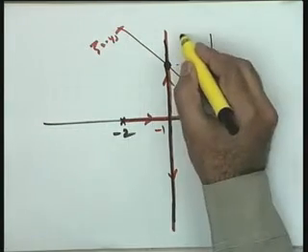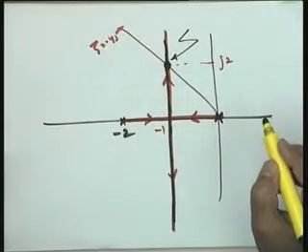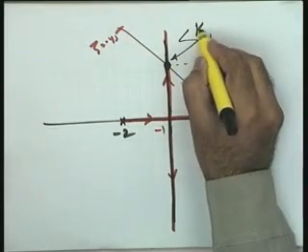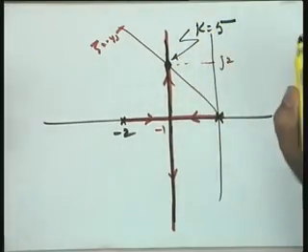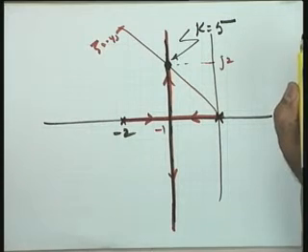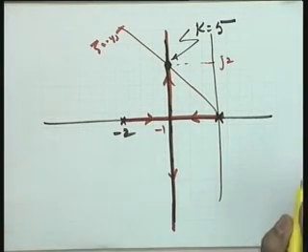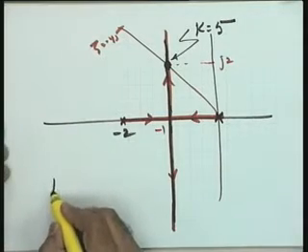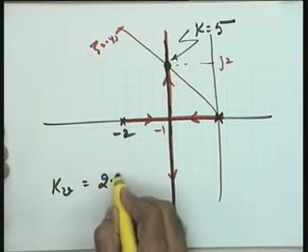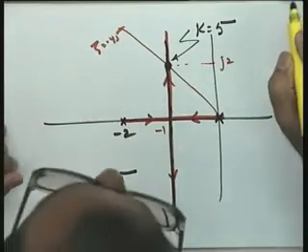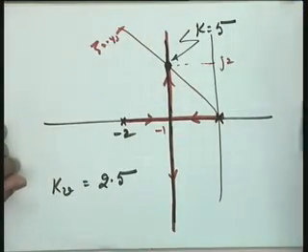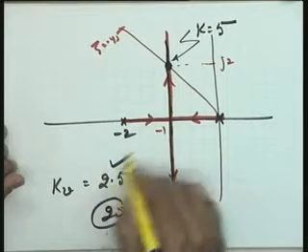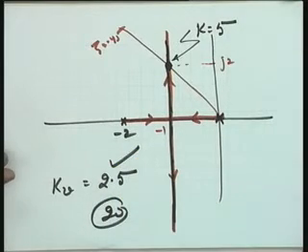Please see. Let me first of all get the value of gain K for this particular case. The gain K comes out to be 5. So it means K equal to 5 satisfies the transient performance requirement. Let me simply check the steady state accuracy. Kv in this case will turn out to be 2.5, because K by 2 is your Kv, which falls short of 20 by a large factor. So the uncompensated system satisfies the transient requirements but not the steady state.